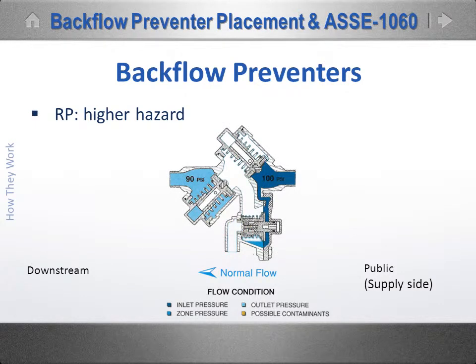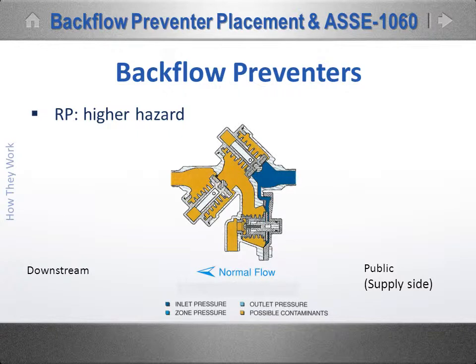Now, some think that that event defines the limit of what water can ever flow into a drain, but boy, that's just not so. Consider a flow stop situation, one that might naturally occur at the end of a workday. If you look closely, you can see that a small pebble has lodged in the number 2 check valve. Because the number 2 check valve is not closing, all the water that has been delivered to the building will continue to flow back out of the relief valve until the private lines are cleared. And if this is a 4-story building, that's a lot of water.